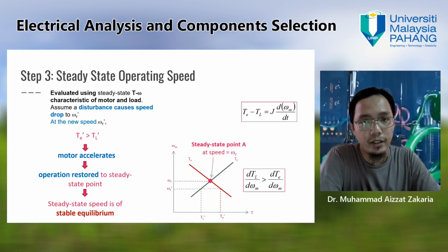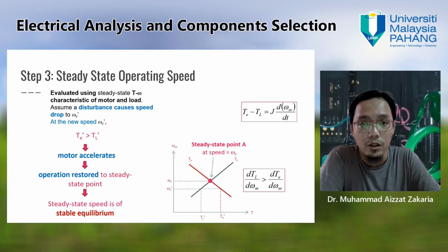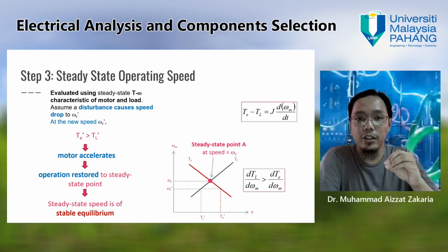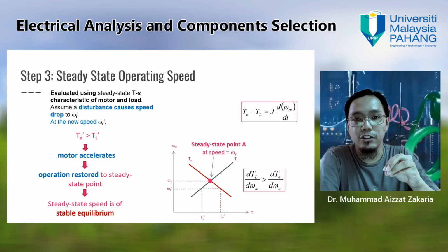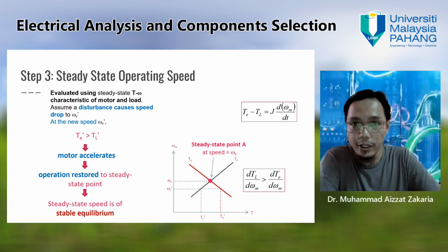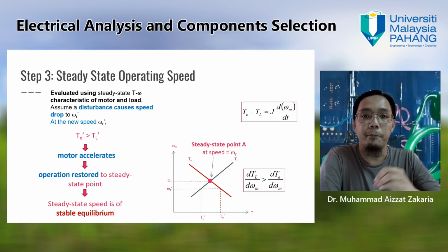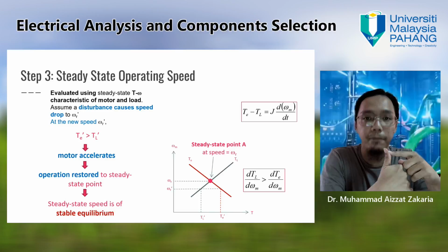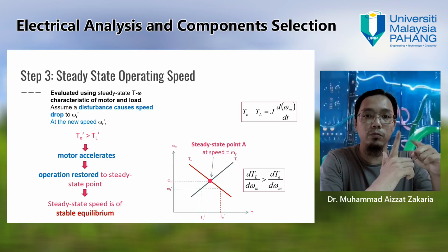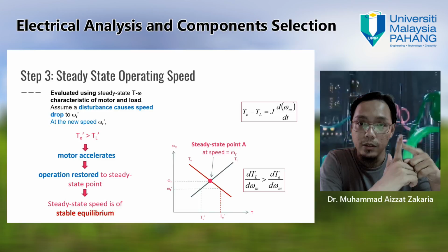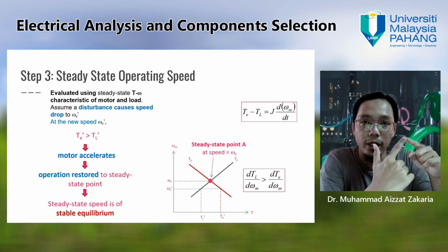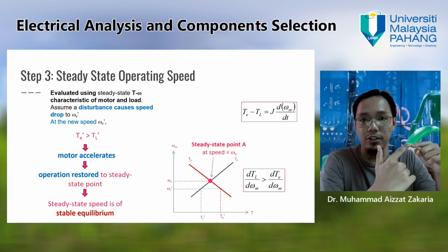For example, you are designing a conveyor system, so you want to estimate the pick and place operation. At what velocity is your item moving, and if you want your item to move at that velocity, you have to understand what kind of torque is required based on my previous calculation.